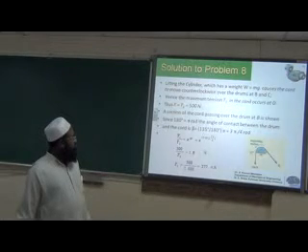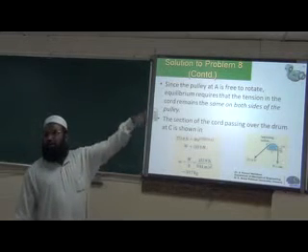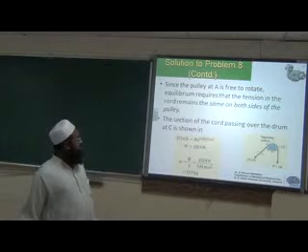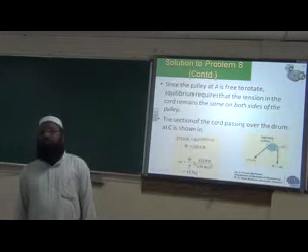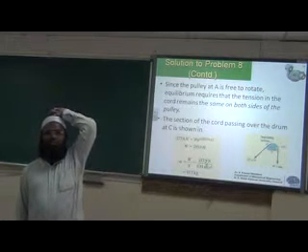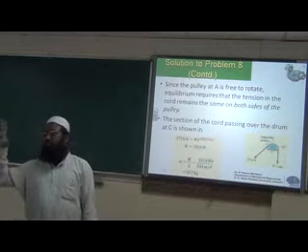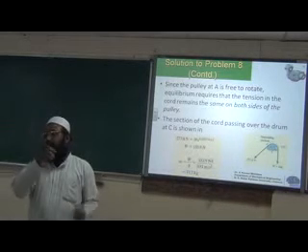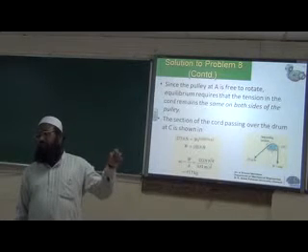So now we have two drums. We consider the first drum and draw its free body diagram. Since pulling is given at the left side, that is considered the maximum tension T1.